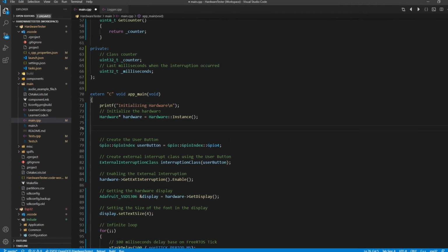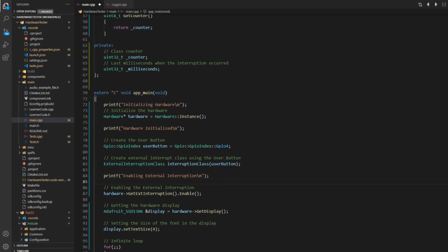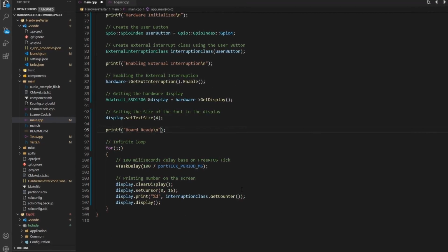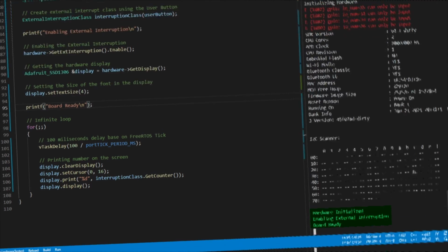Basically, this method involves adding debug messages that will be displayed in the terminal. This is the most simple way to gather information about the execution of our code, and it's useful if you don't have an external debugger tool. The ESP-IDF has a wonderful capability of catching exceptions and misconfigurations, and integrates itself with Visual Studio Code without any extra line of code. Let's take a quick look at how that works.